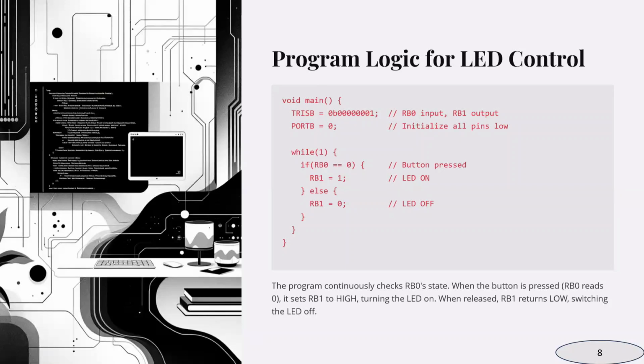Now we are going to initialize the pins. For that, you give PORTB equal to 0. PORTB equal to 0 means the entire port value will be changed to 0, that is, the entire port will be initialized as low. Is that clear? Now you know that to make the program work continuously, you need a while(1), and inside while(1) you will be writing the entire program.